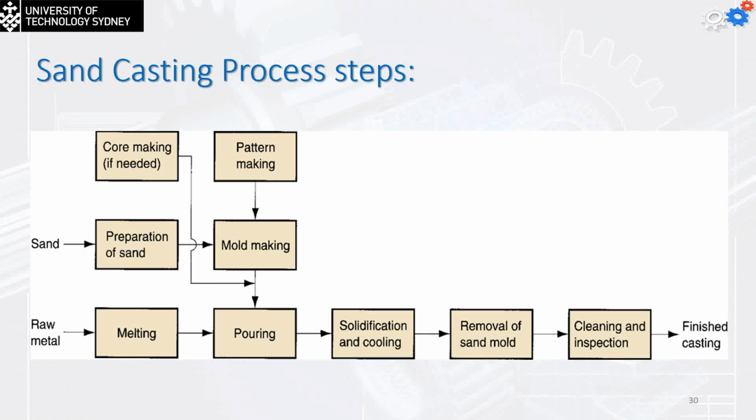And the process for the gray cast iron casting is only going to be limited to sand casting. If I'm going to use aluminum to make the same shape, I can do die casting: aluminum, put in the die, and simply injecting the material to solidify. So these are the steps of making the sand casting. This is a very simple thing.